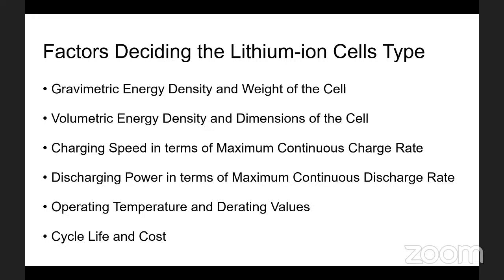I'm traveling across the countries, and I've seen such cells in R&D, but you have to give up on the cycle life. When you take up the silicon graphite anode, the cycle life is lost. That is one of the reasons why nobody uses that in LFP. You could also do that by going with 3 micron copper, because copper also has a decent amount of weight. But then you cannot say I want 10,000 cycles, not possible. So I rightly agree with him.